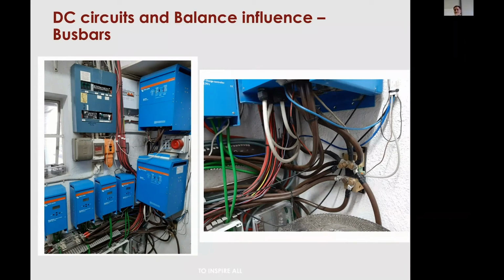So you can see here, even on the BMV shunt, sorry, he had actually ended up putting 2 cables on this lug, 1 cable in this lug, 3 cables in that lug, and another 3 cables in that lug. And in effect, he did not have any preferred path on there.